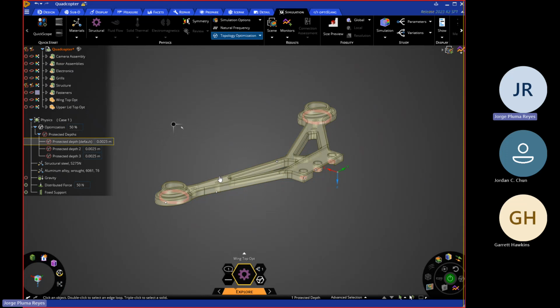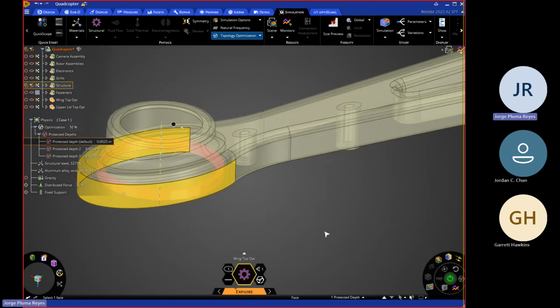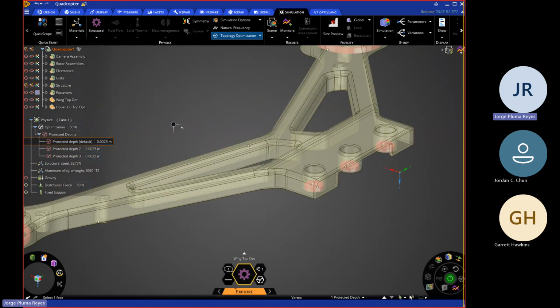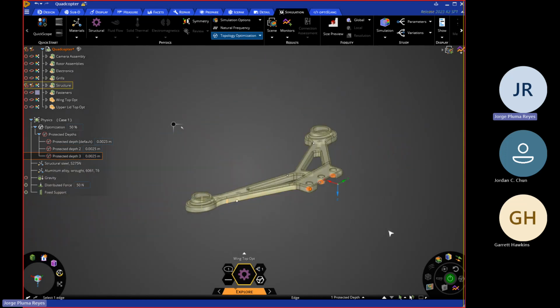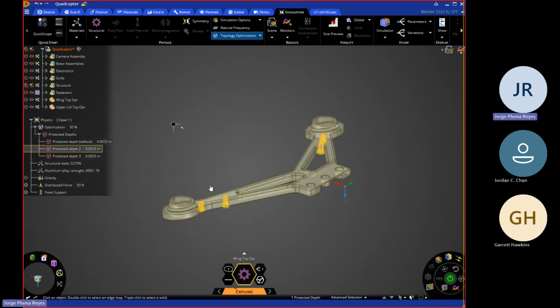And let's make sure that the constraints where the load goes here and where we're constraining to the body are protected. Let's make sure that those bolts are still good, and that any areas that get attached are good. That was done by default, plus some additional ones done by me. And from here, the same problem, right? You just have that force up and some fixed supports here.